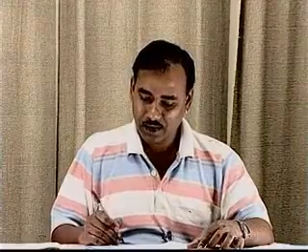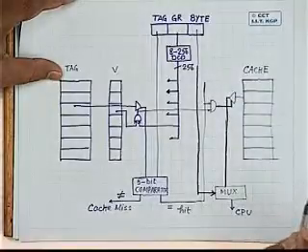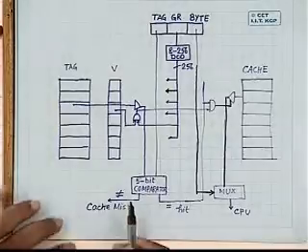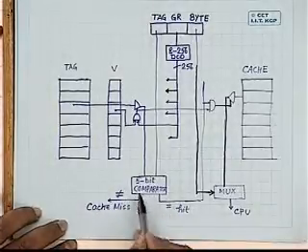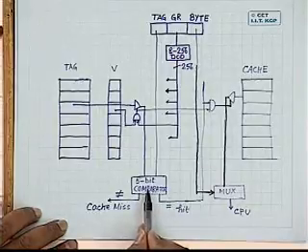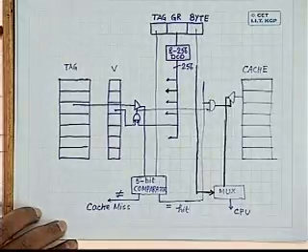Okay. Now when there is a hit, the other part will be again similar to this. So the only thing is the whole thing will be duplicated. So the amount of hardware that you need is twice the amount of hardware that you need in case of direct mapped cache, but naturally it is much less than what you need in case of an associative cache.